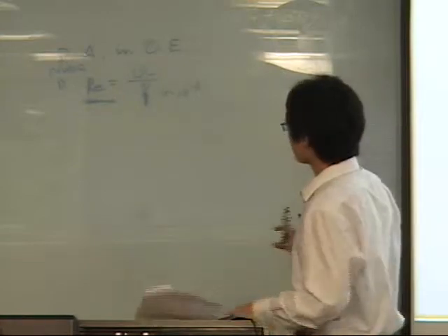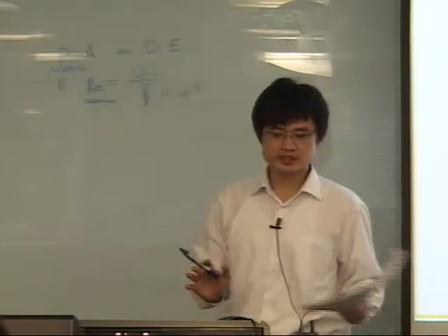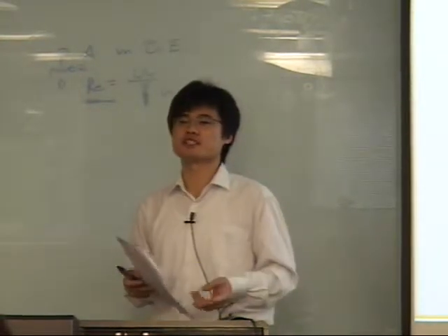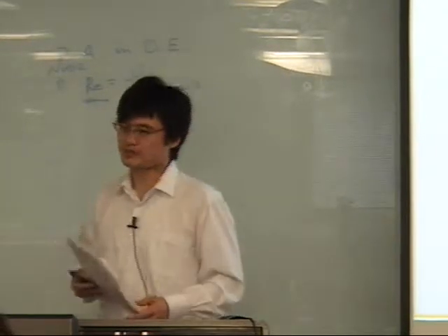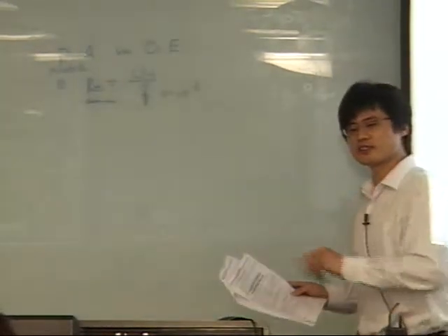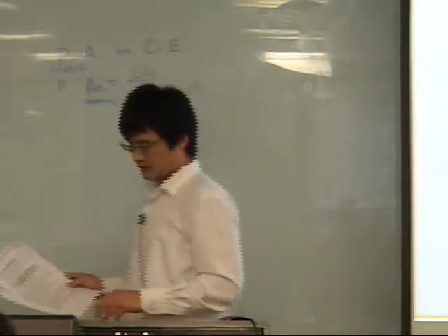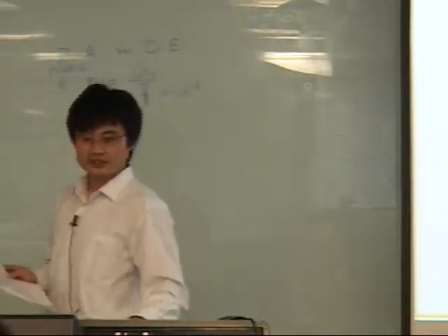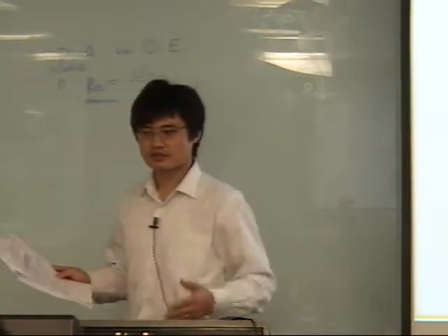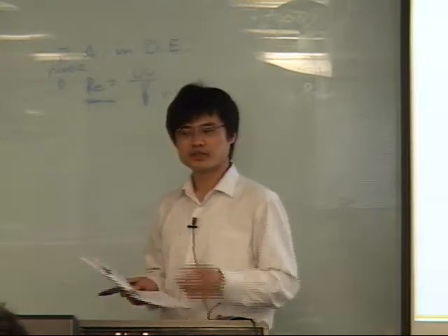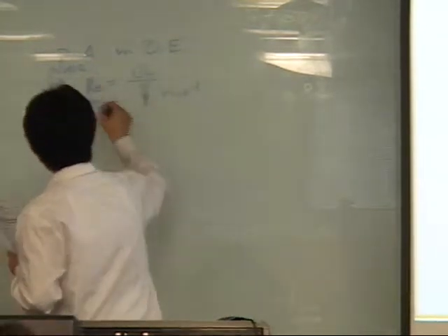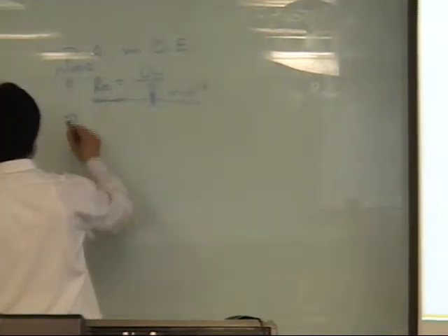That's the reason we can use diffraction theory or other methods to compute wave loads without considering viscosity. And that's the reason we can assume the fluid is inviscid. This is in general true. But if you are considering boundary layer problems, or large ships with large frictional contact with the water, you have to take that into account. But this is in general something we noticed from the dimensional analysis.